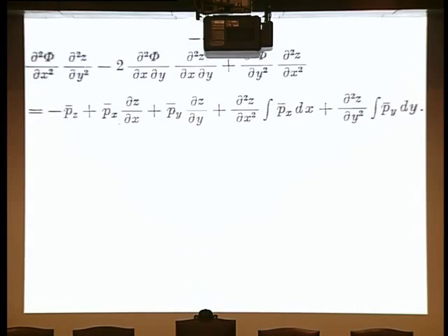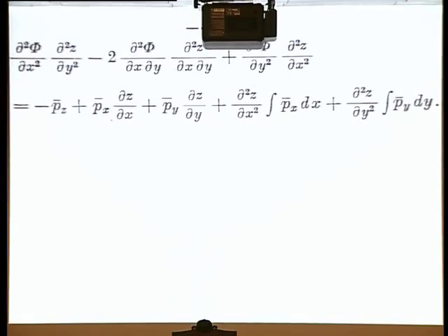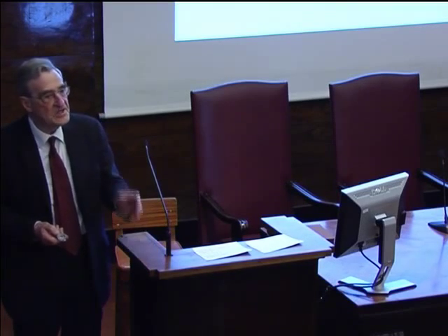First of all, these terms on the right-hand sides in P, those are the loading terms acting on a particular structure, and they need not concern us at all here. This is a partial differential equation, second order, for those of you who know mathematics, to determine this function phi from this equation. And once the equation has been solved to give the value of phi, then we know what those stresses are that we showed on that previous element. The pulls in the two directions and the shear stresses can all be determined from that.